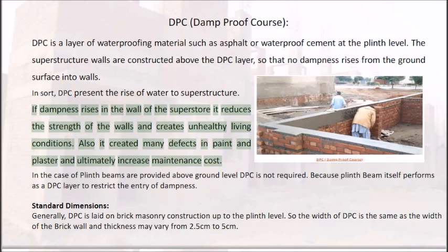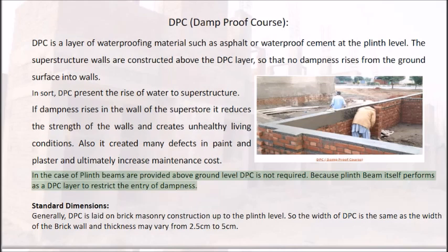In the case of a plinth beam provided above ground level, DPC is not required, because the plinth beam itself performs as a DPC layer to restrict the entry of dampness. Standard dimensions.